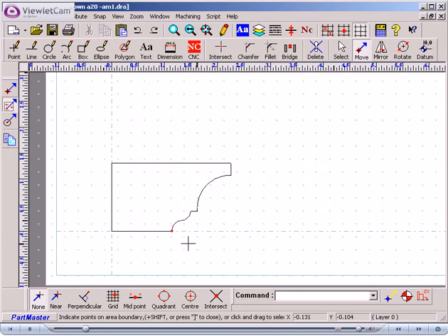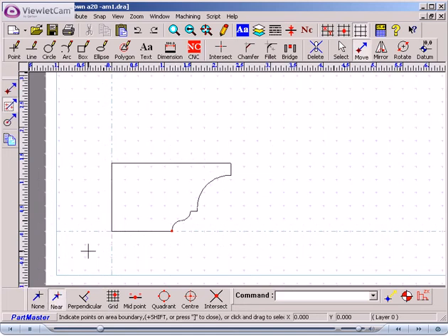There's nothing to say, of course, that the shape that we've got is currently relative to a grid position. So what we can do is move the grid origin such that it starts at this corner here. To do that we use Grid Origin, go into Near Snap to lock the grid onto that bottom corner. So now the grid lines up with the component.